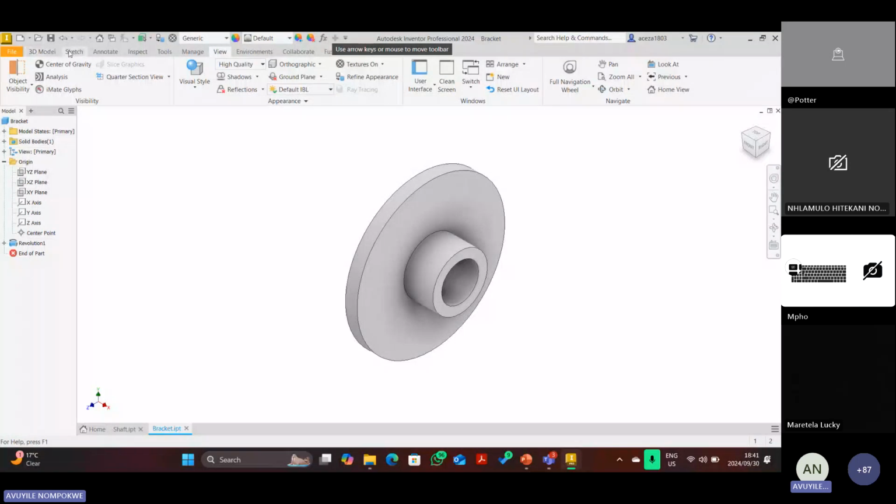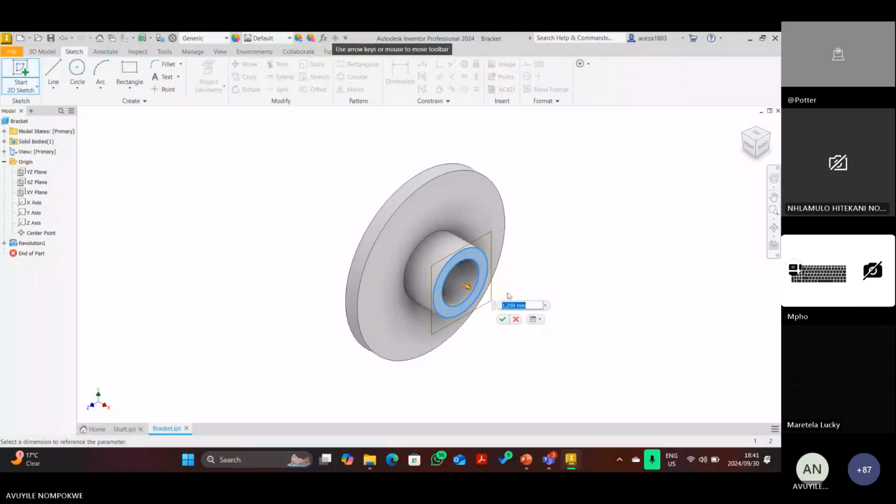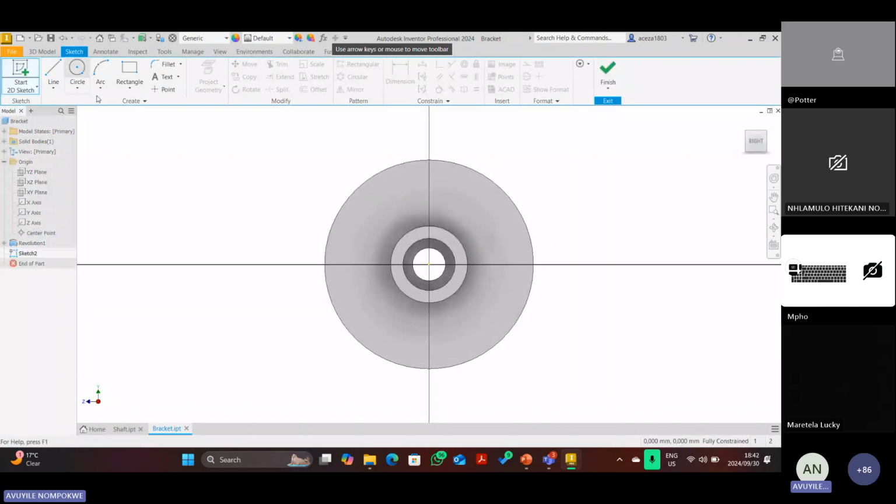So now we need to start a 2D sketch here on this surface, right? And then we can just project this geometry because we know that it's already diameter 54. This one is 56, radius 28, right? And then we need two R11s here, which is 22, right? And also 22. And you know that these ones have to be in the same straight line as the origin.